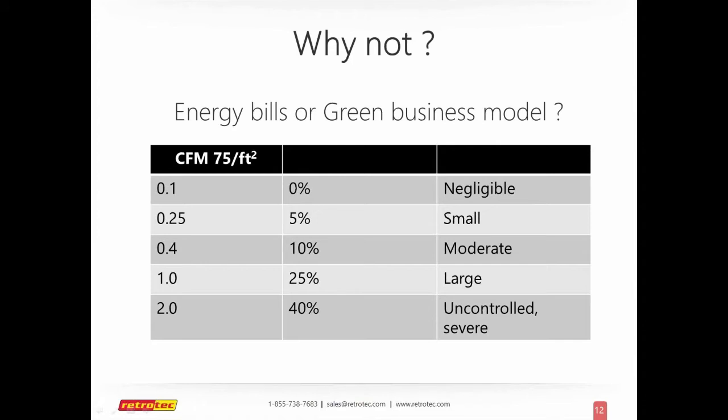So the question is, why not? I took my energy management course almost 2 years ago, and they talked about light bulbs and HVAC equipment and economizers and chillers and more things that I can never imagine. And they went back to lighting again, and out of the entire 4-day class, nobody talked about testing the envelope. I was stunned that that was not part of how they imagined that you could actually reduce your energy load, or most people don't want to pay for comfort. They want to see what their payback is, and it's shocking how well you can actually pay back part of your commercial property or your large structure by reducing your infiltration.